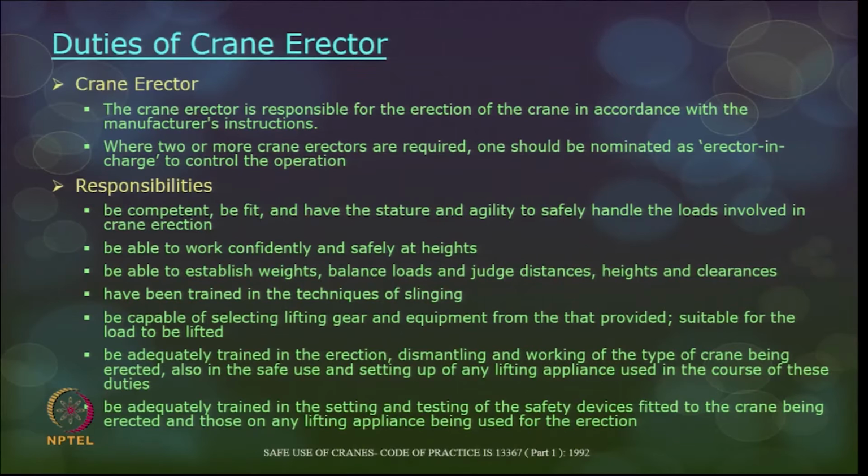Responsibilities of the crane erector: he should be competent, fit enough, and know how to handle cranes. He should be able to work confidently and safely at height, preventing fall hazards and so on. He should be able to establish the weight, how to balance the load, and judge distance, height, clearances and so on. He should be able to manage the complete operations properly, be trained in the techniques of slinging, and be adequately trained in erection, dismantling and working of the type of crane being erected, and also in the safe use and setting up of any lifting appliances in the course of all these duties.